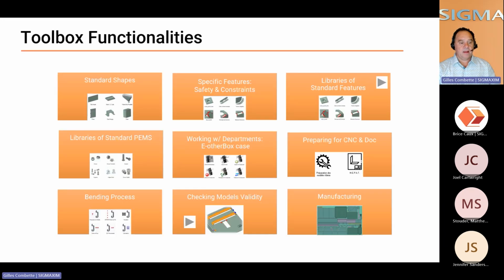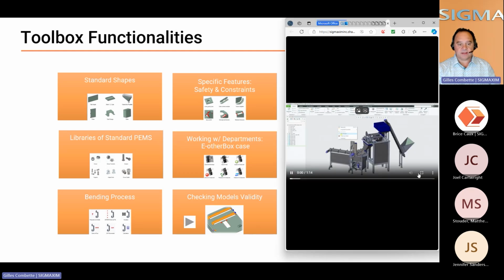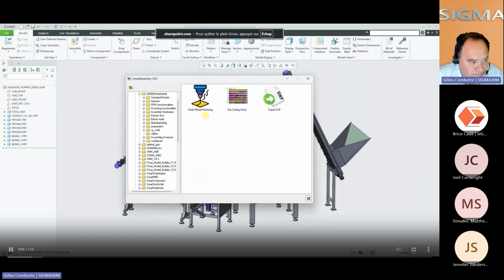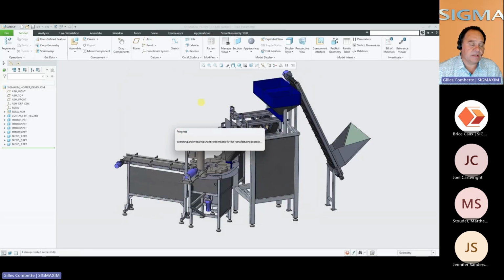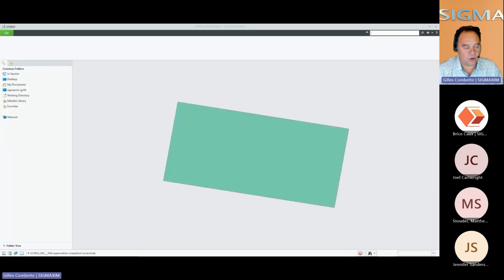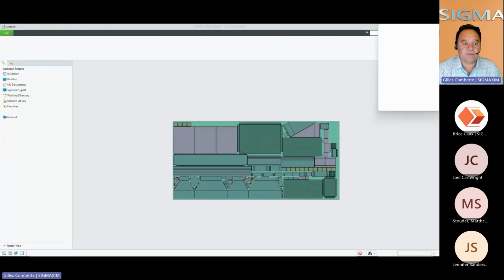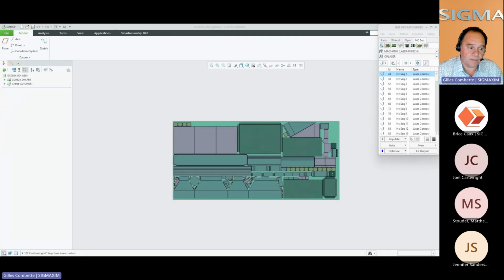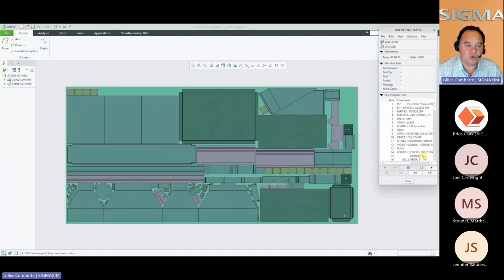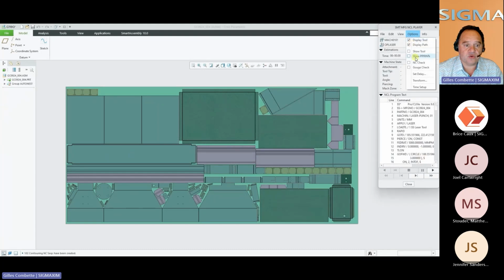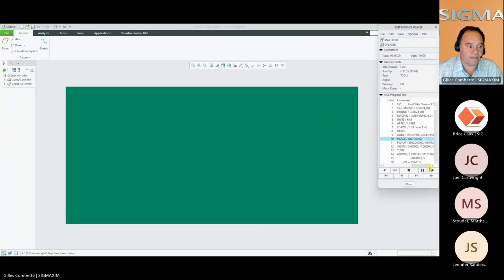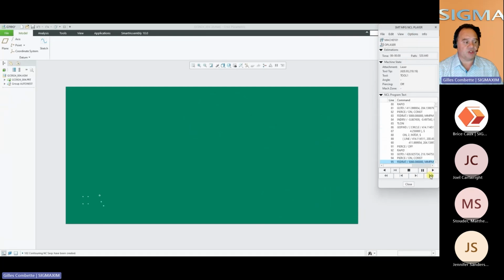And if now you are lucky enough to have Creo NC sheet metal, it is as well a possibility to automate the complete process from the design to the manufacturing. Here, what is happening, the solution is searching all sheet metal models from the assembly. It's organizing them by thickness, and then it's preparing a nesting. And the nesting then will be used to automatically generate a laser toolpath on it. Here we did a laser toolpath, and we have the simulation of this laser machining that is done here.